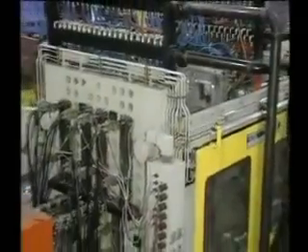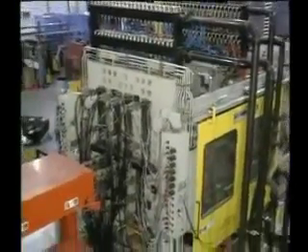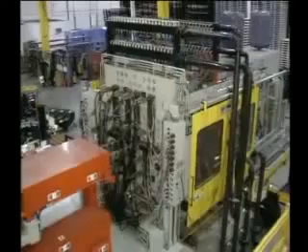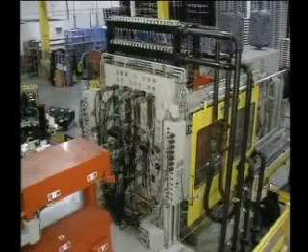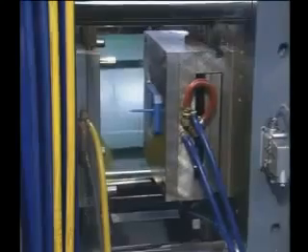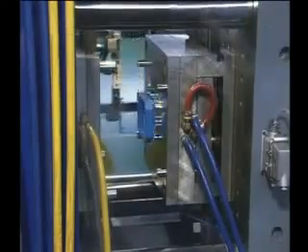Thermosets undergo a chemical reaction between two reagents when heated and achieve their strength through the interlocking chemical bonds. Once molded, thermosets cannot be resoftened. While thermosets are injection moldable, most materials used in injection molding machines are thermoplastics.